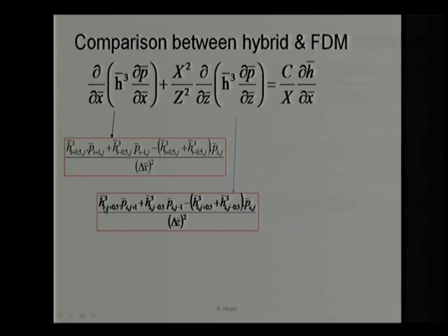So, what we can write here is again a similar form. Instead of i, here we are writing j. Okay. So, i will be as it is, and j will get an additional node, the j plus 0.5, the half node for the j direction. Similarly, here instead of p i plus 1 j, we are writing p i comma j plus 1. Same thing over here, and again same thing over here. Next, similarly, we can take a central difference method for this pressure and this film thickness gradient h i plus 1, h i minus 1.